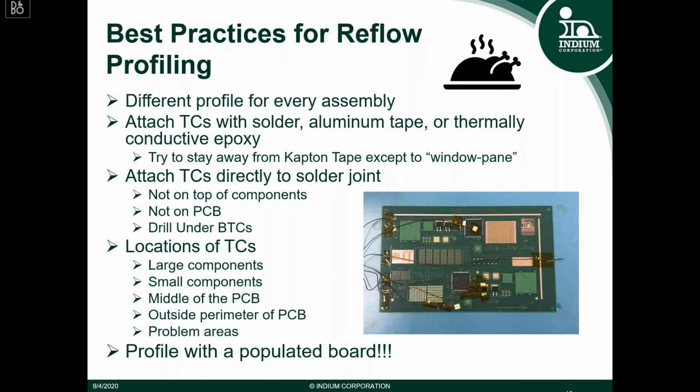In the image here, you'll notice that I have one thermocouple attached to the QFP. In certain cases, you may want to know what temperature the component might be exposed to if it's a temperature-sensitive component. This is an instance where you may want to attach a thermocouple to the top of the component, and the same thing goes for the board. However, if you're reflow profiling for the purpose of optimizing the solder joint, then you're going to want to make sure that the thermocouple is attached to the solder joint itself.